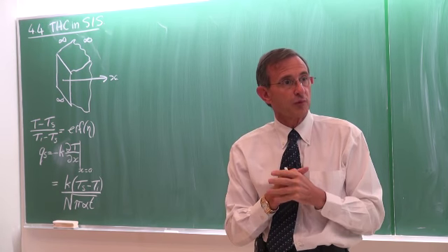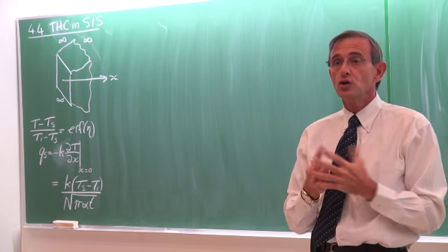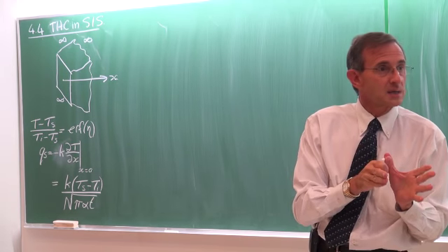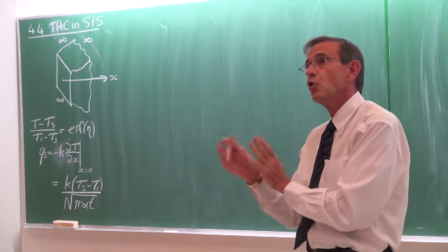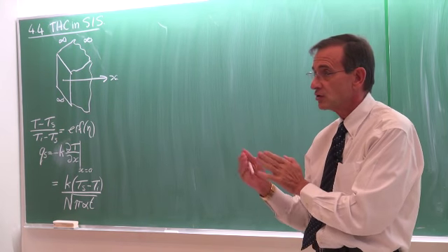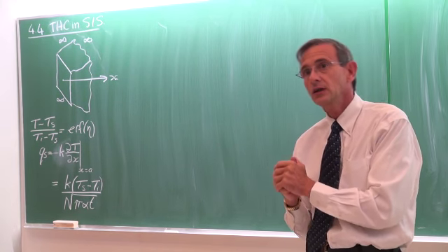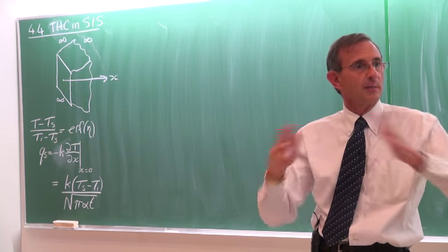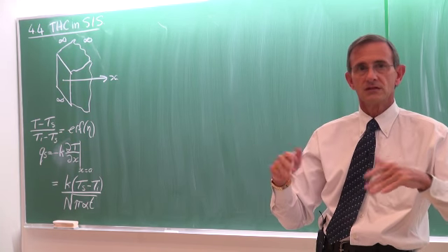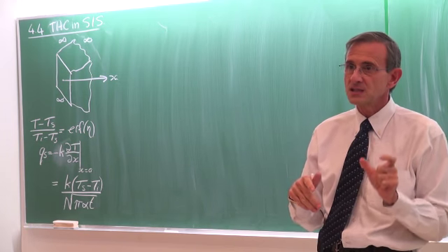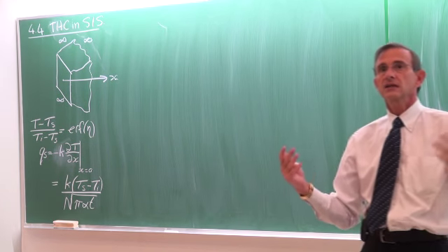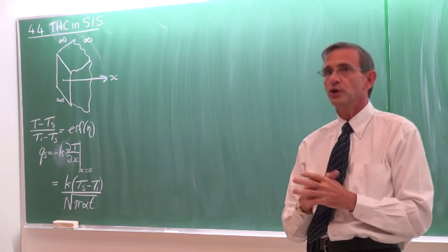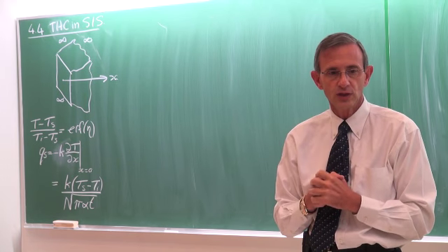Those categories of problems would occur if the thermal resistance of conduction inside a body is much smaller than the convection heat transfer on the outside. A good rule of thumb is about 10 times. So if the resistance on the inside is 10 times smaller than the outside, then that is the Biot number, which is 0.1. So that is the criterion that we use.